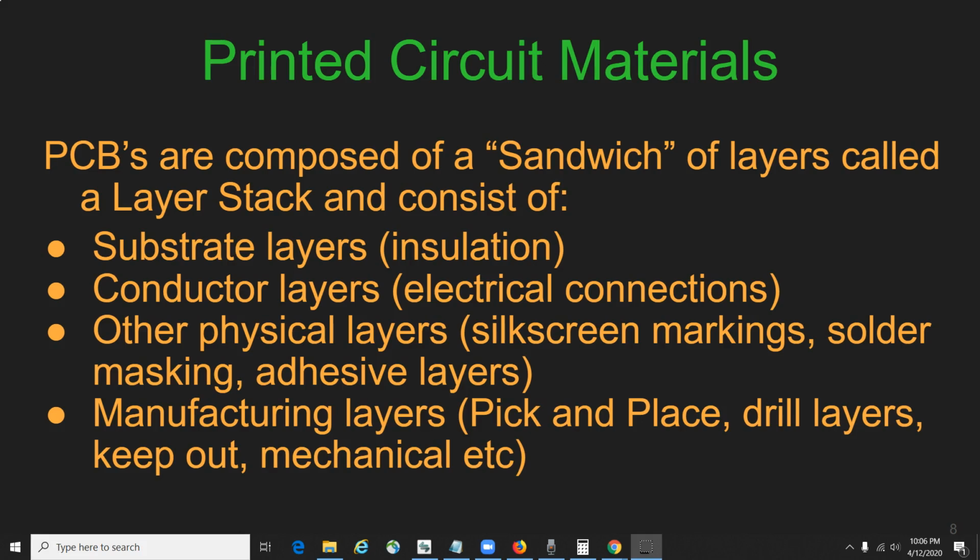Solder mask basically provides a thin layer of polymer. It is used to provide protection against oxidation and to prevent solder bridges from forming between closely spaced solder pads. And then the adhesive layer is basically used to provide bonding between the substrate film and the copper conductor. In some cases, especially double-sided flexible PCB design, the bonding area also can be adhesiveless.